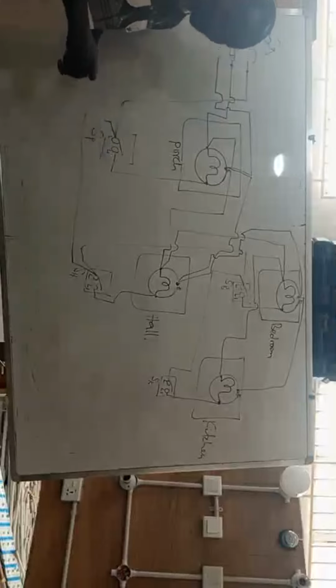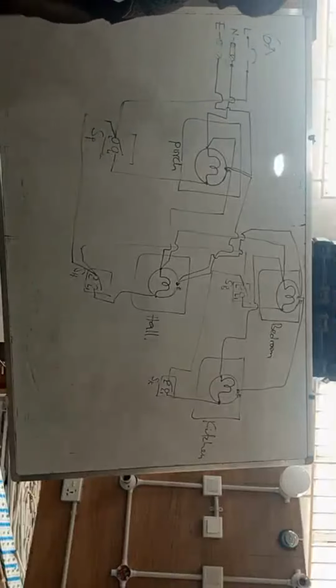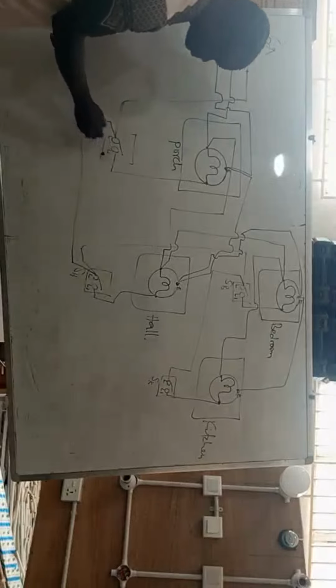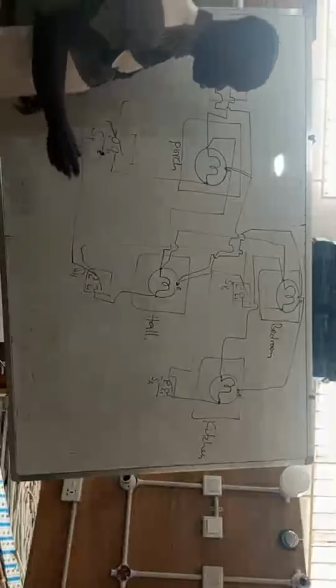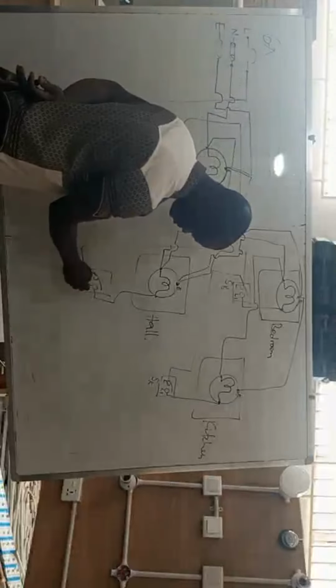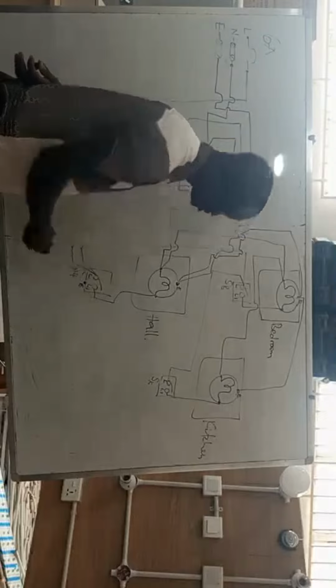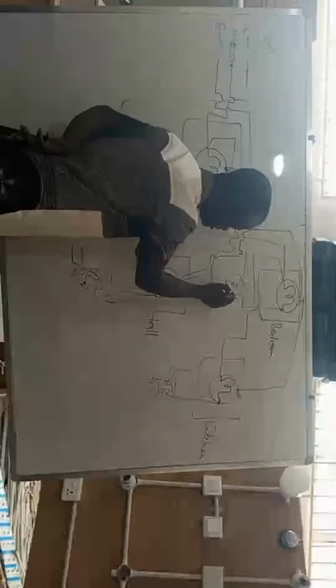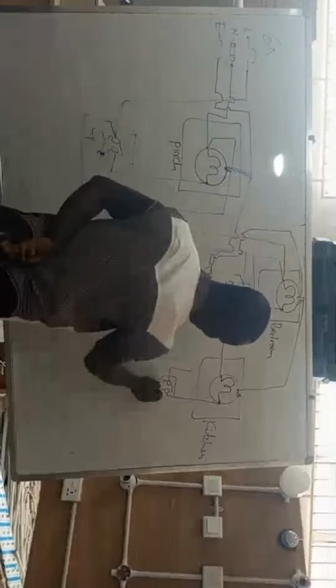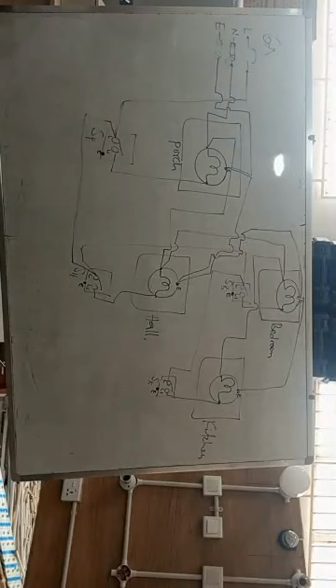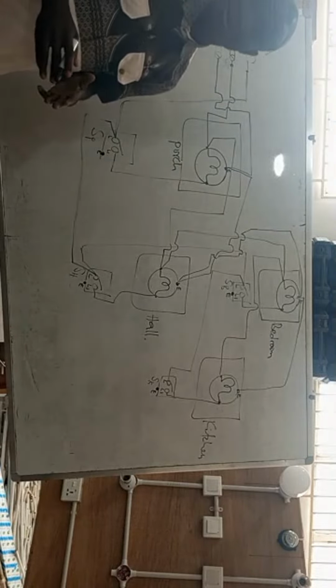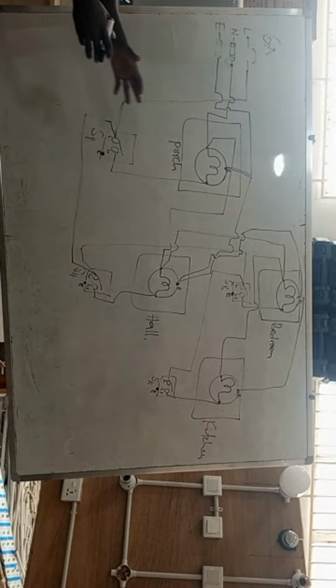If you observe closely, when you buy those boxes, they have their own terminal connection, an earth connection point. Okay? So this is the earth connection point of this box. This is the earth connection point. This is the earth connection point. It's usually located at one of the corners of the box. So if you look carefully, you'll see it.